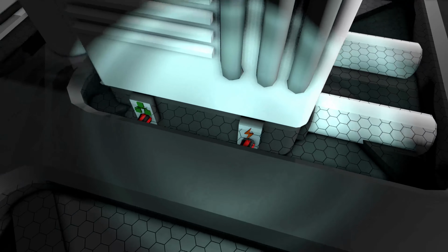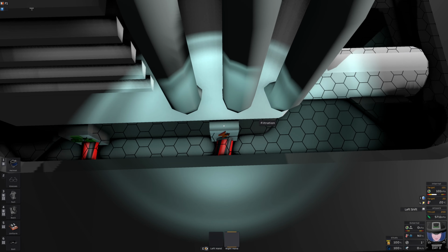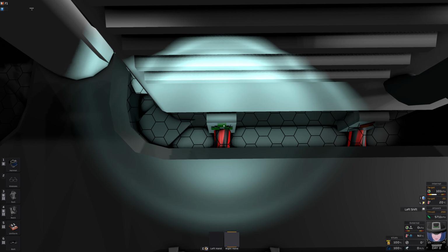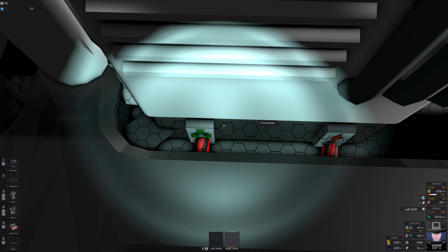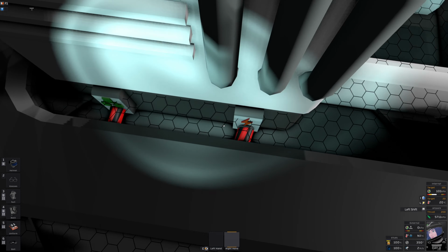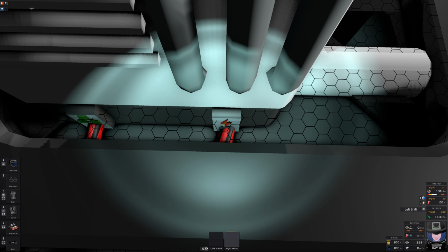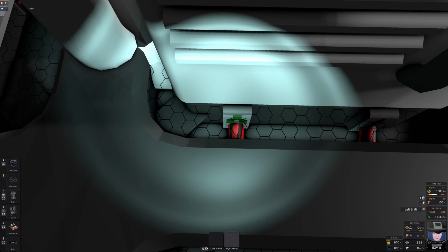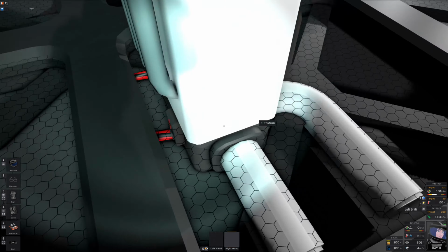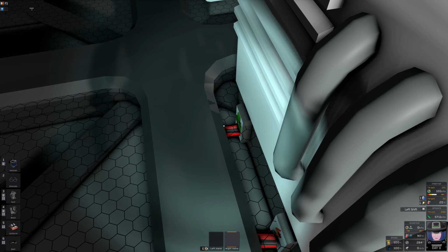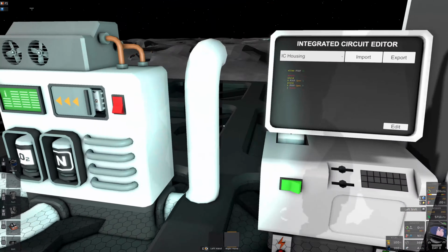To control a device with logic, you need to not only connect its power, but definitely also its logic connector. Many devices have those combined, so if there's only one connector, that's for power and logic, always. But if there's two, well, if this one's not connected, then there's no use debugging your program, it cannot work.